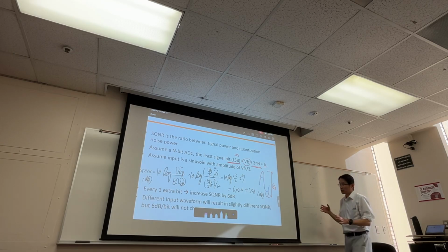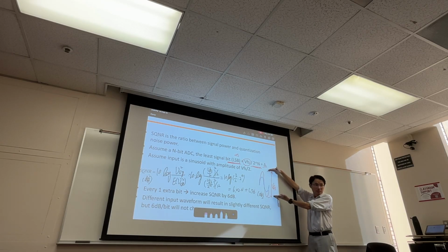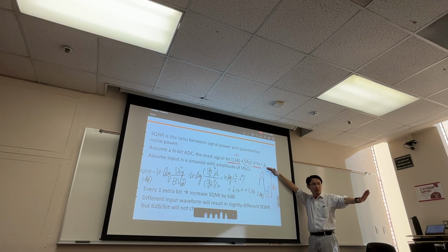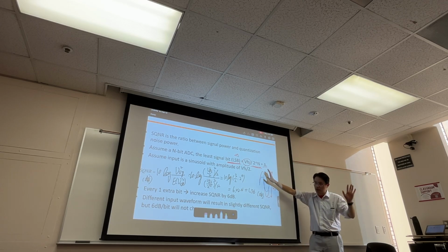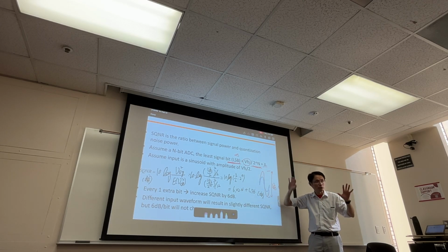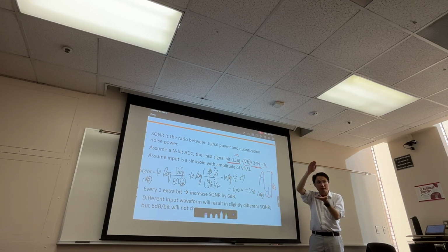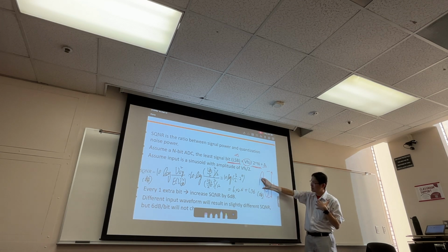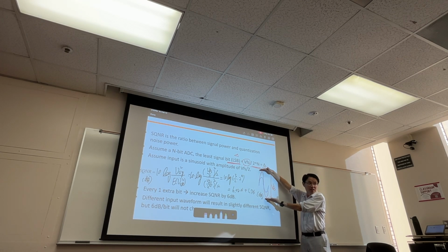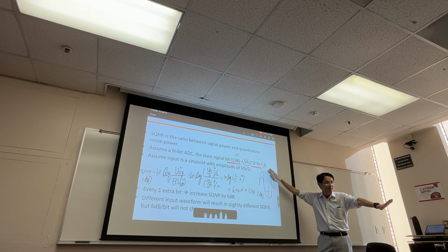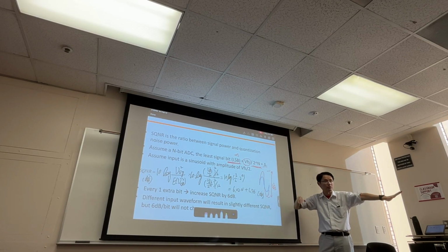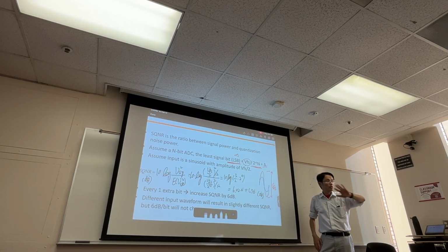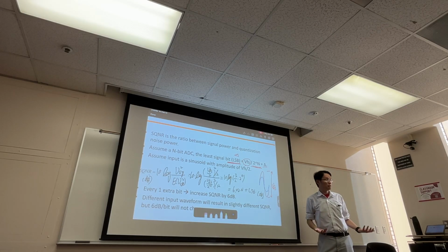So you design an ADC with this 1 volt swing. If you decide that, okay, let's not forget SQNR, try to specify what's the upper bound, right? What's the maximum SQNR you can get. In order to get the maximum possible SQNR, of course, when you inject the input, you have to inject the full swing scale so that you can max out your input signal power. Does that make sense? But it doesn't mean that you always need to do that, right?